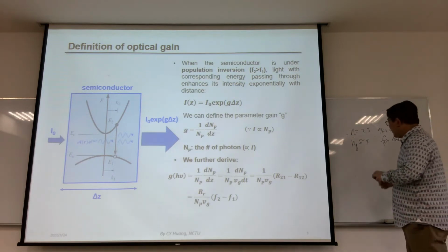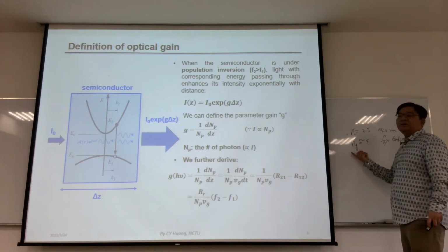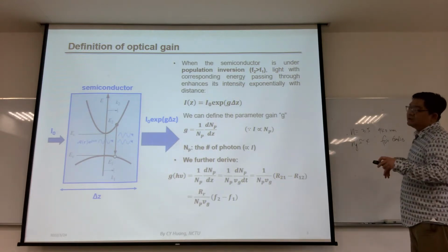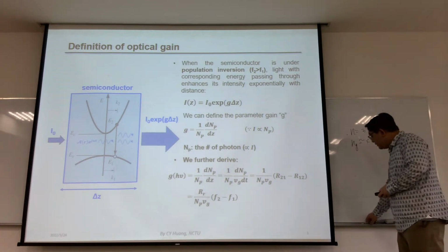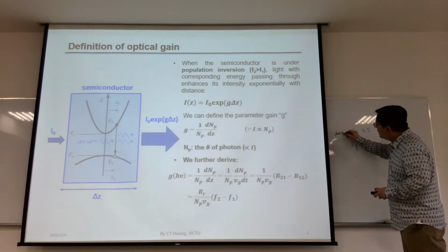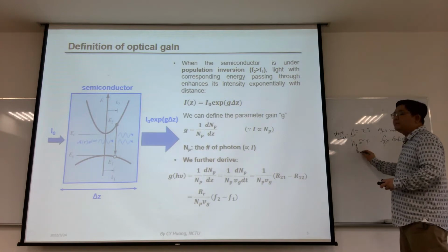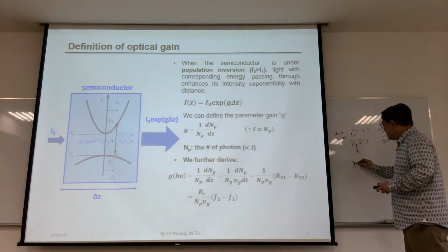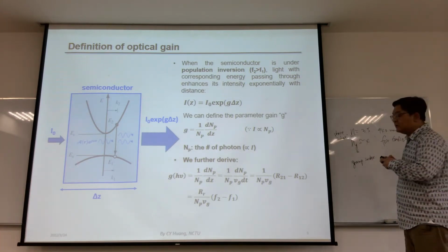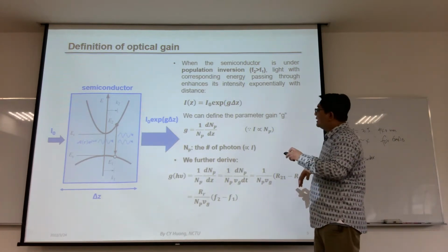So while you're doing the calculation, remember that you need to calculate the gain with the group refractive index most of the time. But in the following one it will be different, if n is the phase index, while the g at the bottom is the group index. So while you're reviewing it, you need to take care of that. Sometimes it will be misleading.